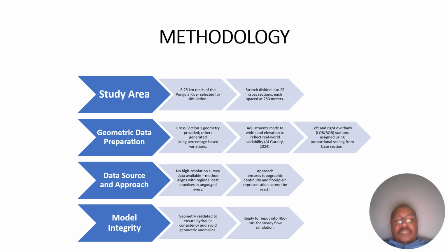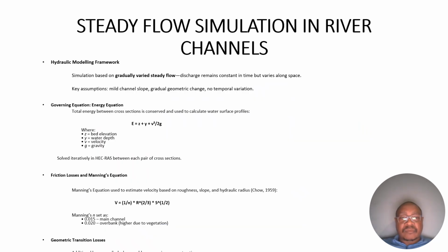represent across the reach. And lastly, on the model itself, the model integrity, it's the geometric validity to ensure the hydraulic consistency and to avoid geometric anomalies. And lastly, ready for input into the HEC-RAS software for steady flow simulation. That is the methodology of the assignment.